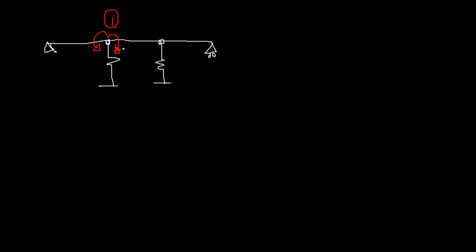If you add a bending moment like this, it is a unit bending moment, right? Not a unit rotation. Theta is not 0, but the M is 0. So this is going to be like this. This is going to deflect like this. This part has not any effect, right? So if you apply a unit moment like this, you can just take bending moment about this point.